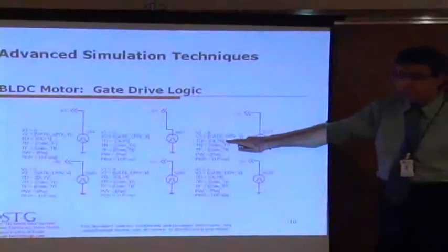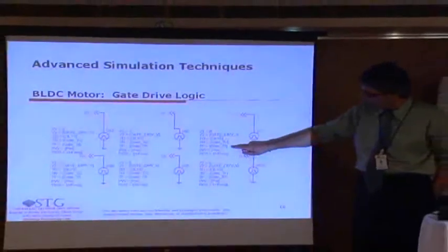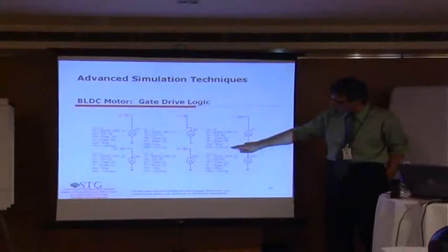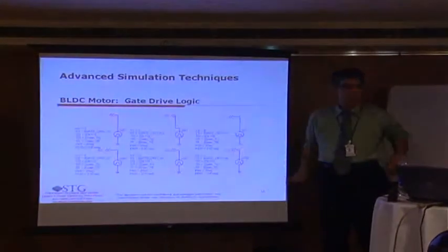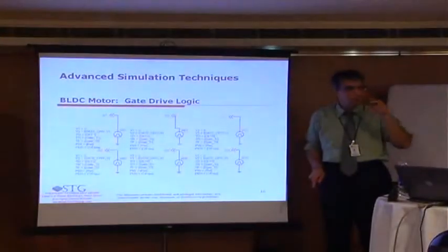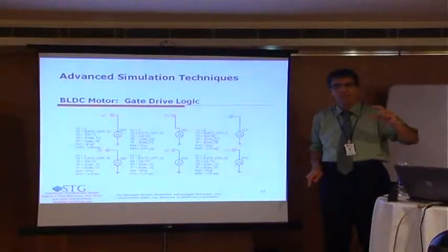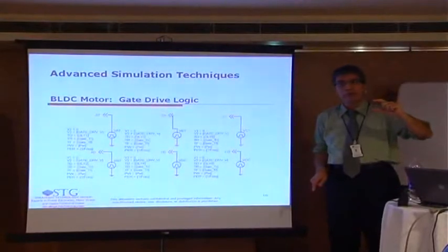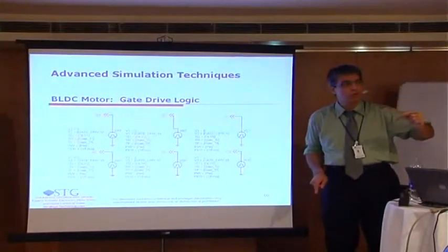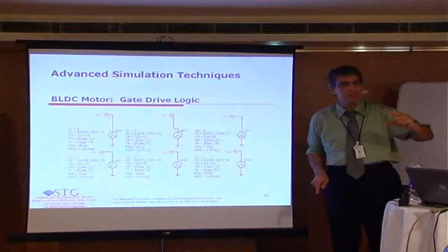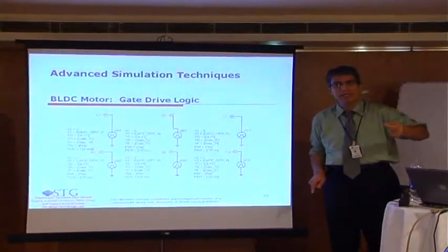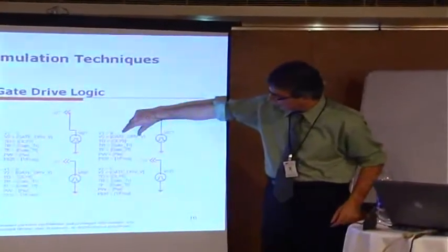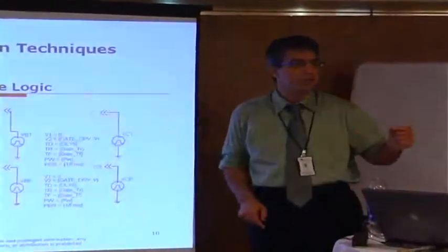And then you have a delay time, a rise time, a fall time, a pulse width time, and a frequency. So these parameters are defined in a parameter file. We'll show you in a minute what the parameter file is also. Now, we tend to store all of these parameters in a parameter file so that they can be easily changed. We can essentially perturb any of these parameters when we're running a simulation.